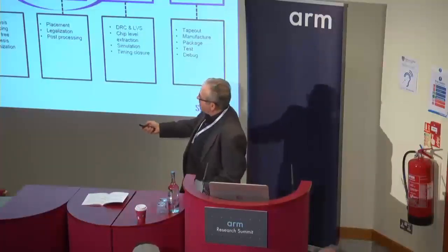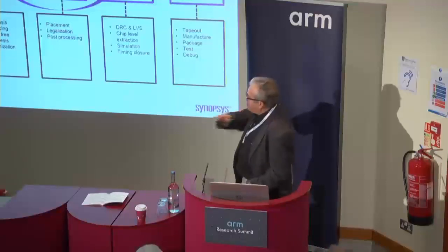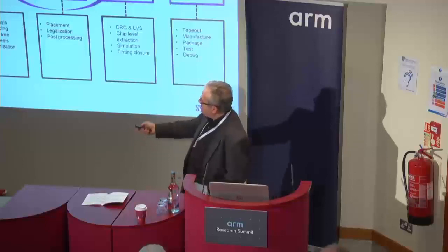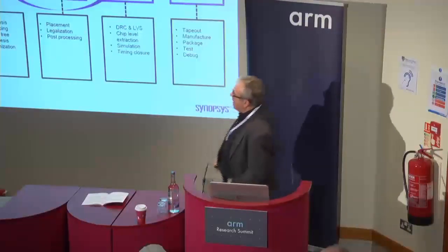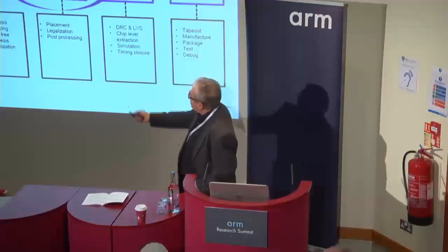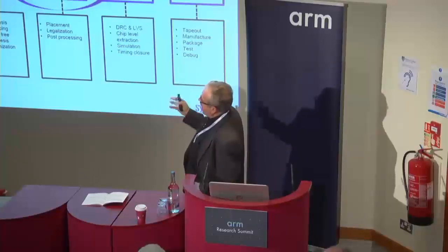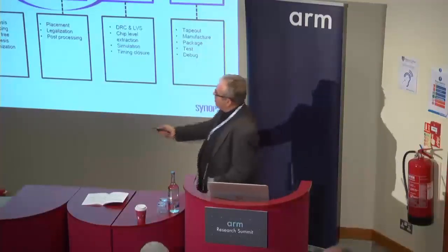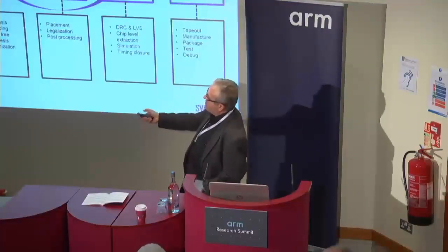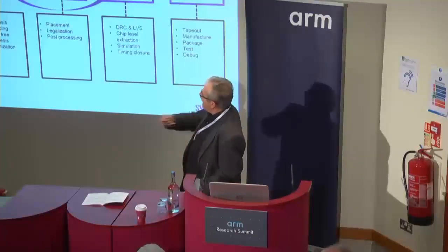Here, what we do is start with ab initio, essentially basic physics, just very preliminary equations, and generate what-if situations. Based on that, do SPICE modeling, including Monte Carlo variability, take it through the full library development, and further through a full design cycle. Based on this what-if scenario, with the SPICE model distribution, it gives you feedback as to what is your best material of choice, what tweaks you need to make to the process before you even fab any silicon.